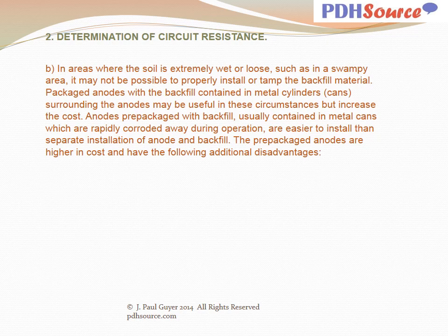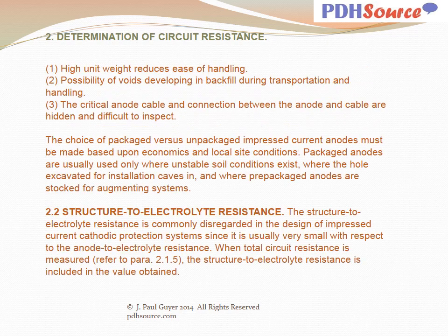Anodes pre-packaged with backfill, usually contained in metal cans which are rapidly corroded away during operation, are easier to install than separate installation of anode and backfill. The pre-packaged anodes are higher in cost and have the following additional disadvantages.